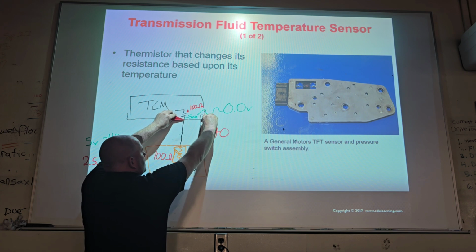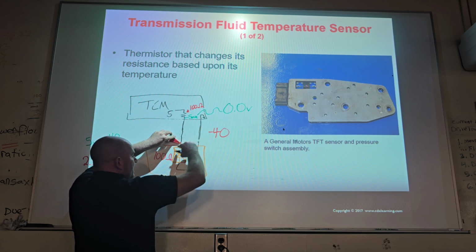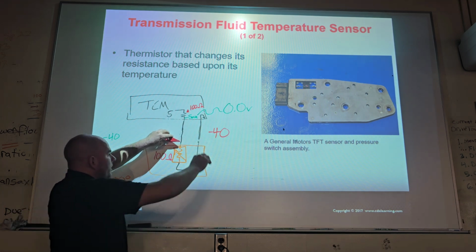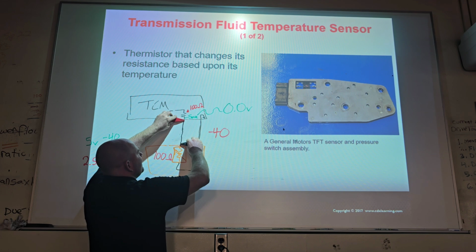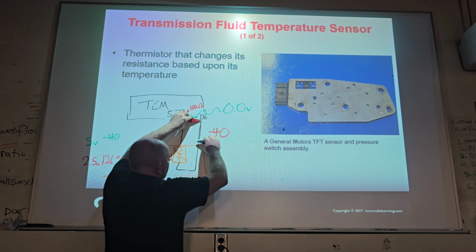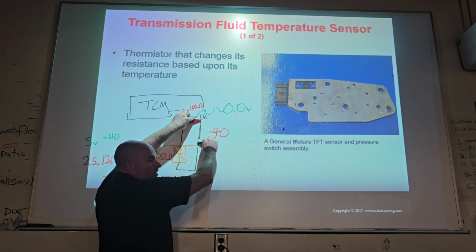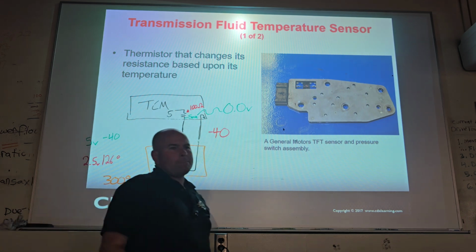But if I measured 0 ohms here and then I came down here and I measured 100 ohms, what would that tell me? Not in the transmission. Exactly. So now what should I do? What should I get? Like 0, 0.2 maybe. If let's say I got 0.2, what should I do next? Let's say I got OL. Needs a harness, right? You can. It's up to you.